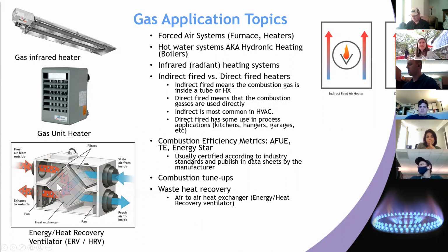This is an example down here on the left of waste heat recovery from exhaust air. This is pretty common in commercial HVAC use, where the air that's inside is already warm and toasty. So you run it through a cross-current heat exchanger to pick up some of that heat from fresh air, ventilation air that you're bringing in. But this is just one example of a very common packaged box solution. When you're working with a manufacturing process, it can be a lot more tricky to get waste heat recovery implemented.